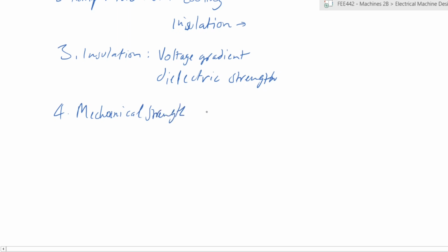So the physical requirements of the machine. Generally, as you have rotating machines, they will tend to spin at thousands of RPM. The centripetal and centrifugal forces that the machine is subjected to must be such that the materials that you use can withstand the forces that will be encountered by the machine during its normal day-to-day operation. That must be taken into consideration.